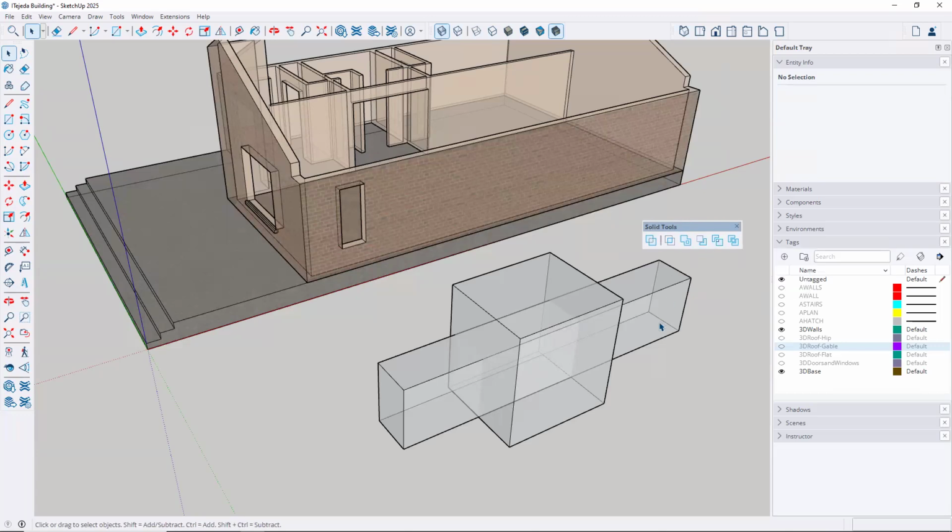So here we go. Let's say that I want to take this long solid here that's cutting through the cube, and I want to just see what it leaves behind. I want that opening or that gap on the inside to be left over. So I'm going to click right here where it says subtract. And when I click on it, it says select the first solid. But before I do that, let me just hover over this for a second. And it says subtract one solid from a second, keeping only the end result. So I don't know which one it's going to keep, if it's going to keep the first or the second.